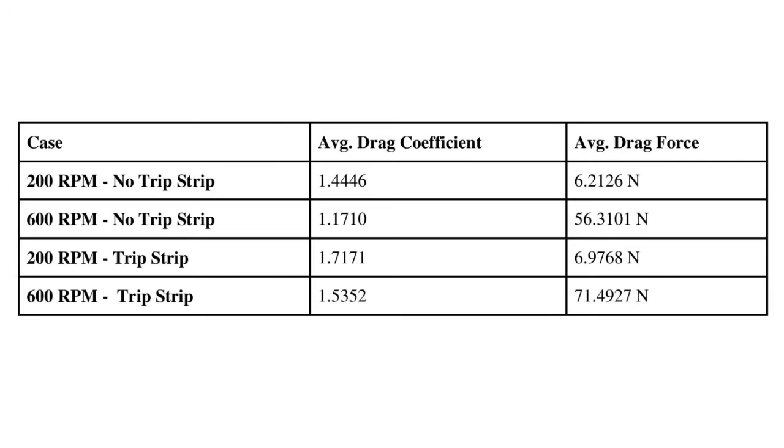However, one interesting point is that all our CDs are in the 1 to 1.7 range, which is exactly the range that the Reynolds number versus CD plot for a smooth sphere that we showed earlier predicted. Finally, note that, as expected, we get lower CD values for higher RPMs or higher speeds. This again is because the higher RPM setting lies in the low transitional regime, which could allow for some of the flow to stay attached longer and thus larger pressures on the back of the cylinder.